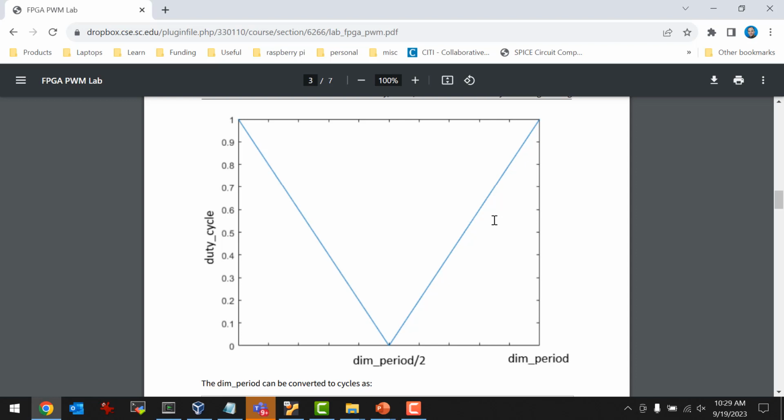But then, whenever you have a signal that you're controlling with PWM, like say you're playing audio, a Class D amplifier, by the way, Class D amplifiers are for PA systems and home audio, broadcast audio. If there were speakers in this room, it would probably use a Class D amplifier. Class D amplifiers are just driven by PWM. So instead of having an analog signal, you actually put a PWM signal out, but then you modulate that to create an audio signal, which itself is another analog signal that has dynamics, right? And that's on a different time scale, right?